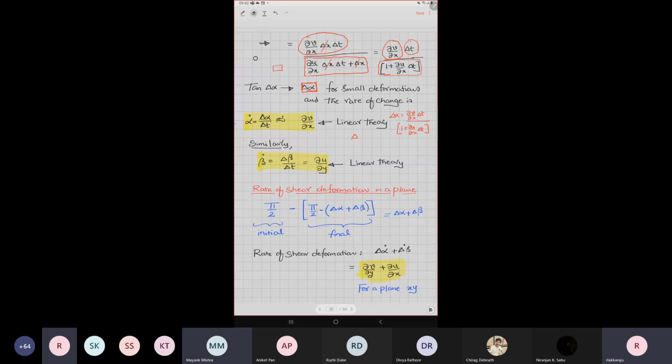So with time, when you apply constant forces and stresses on the system, it continuously evolves. What they decided is, because there is variation with time, it's not a good idea to keep the time component in the picture. Can I ask myself the rate at which this angular deformation happens? For that purpose, you are calculating delta alpha, so to eliminate time, let us calculate delta alpha by delta t. The rate at which angular deformation happens for the fluid is the limit as delta t tends to 0.